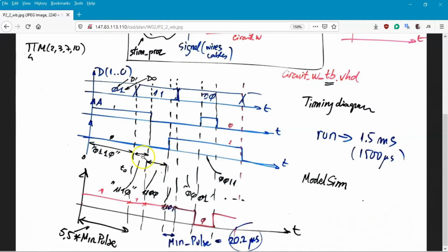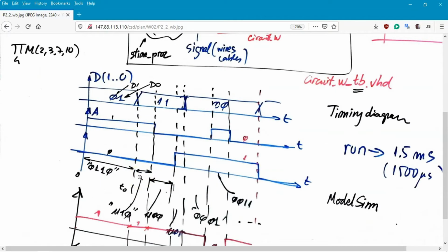Because now, if you have this on paper, it's only about translating this diagram, this timing diagram. Let's translate it into VHDL. And you see, the translation consists of applying different values to the inputs in time and keeping them for a while. How long do you have to keep the signals? Well, for example, this is a minimum time, or that one here, this time is even smaller, that one just a little bit smaller, right?